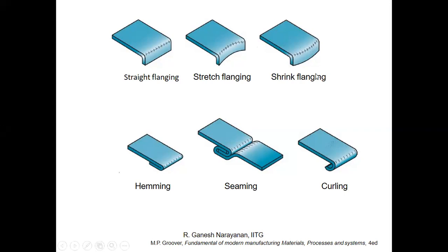It is very much possible that we have another sheet in between. So this hemming would ensure that the sheet and this particular blue sheet are intact. They don't move relative to each other. Hemming is one of the most important techniques in the automotive industry, especially BIW. Car doors, etc., are hemmed.